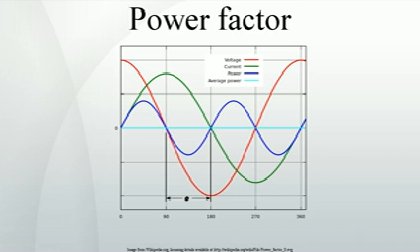An automatic power factor correction unit consists of a number of capacitors that are switched by means of contactors. These contactors are controlled by a regulator that measures power factor in an electrical network. Depending on the load and power factor of the network, the power factor controller will switch the necessary blocks of capacitors and steps to make sure the power factor stays above a selected value.